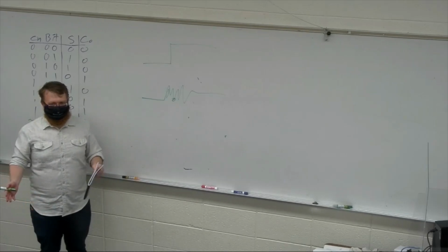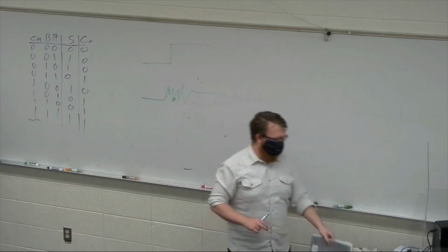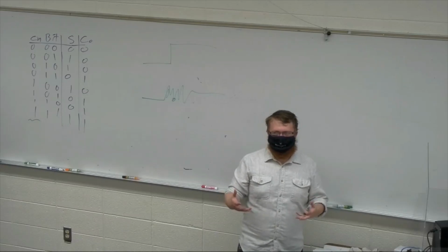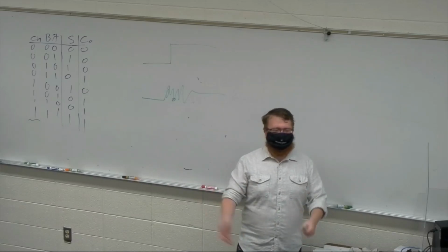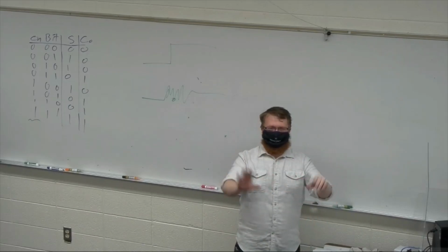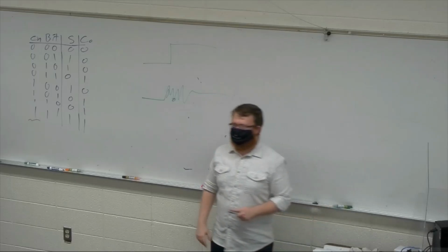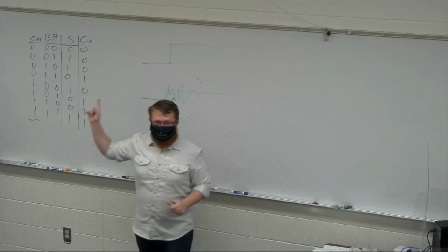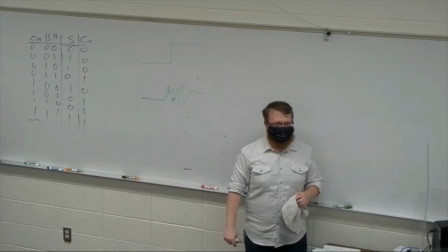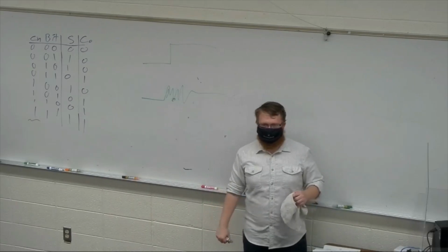It's a very easy solution. And honestly, a lot of times if you go work at a big company, they'll just hand you a package of pre-written VHDL. Anytime you interface a button, you do it through this module. It'll be called something like push button or dip switch, and you just throw that on any of your outputs or inputs. But it's an issue to be aware of, so that if someone asks you how you solve debouncing, you could say, I would use a state machine to wait for the bouncing to be over and then take the sample of what it's supposed to be.